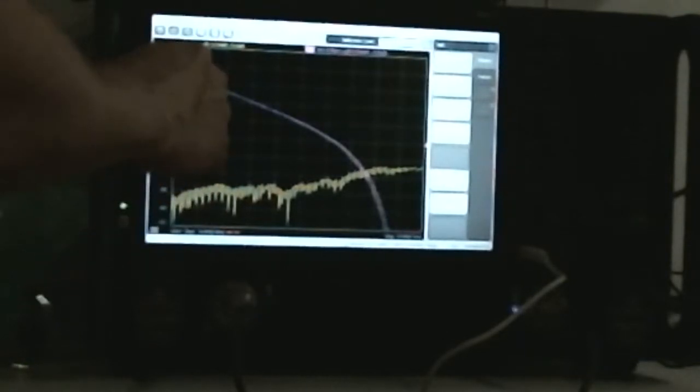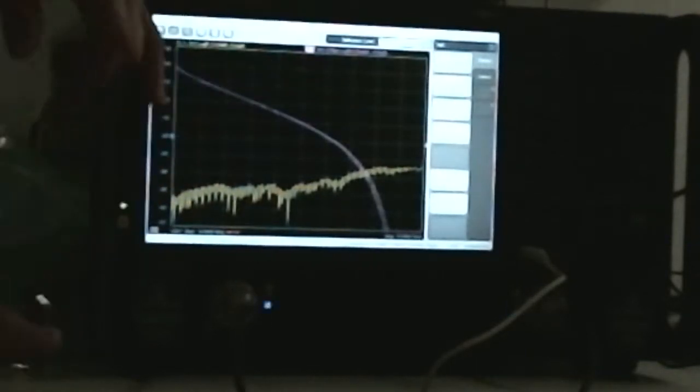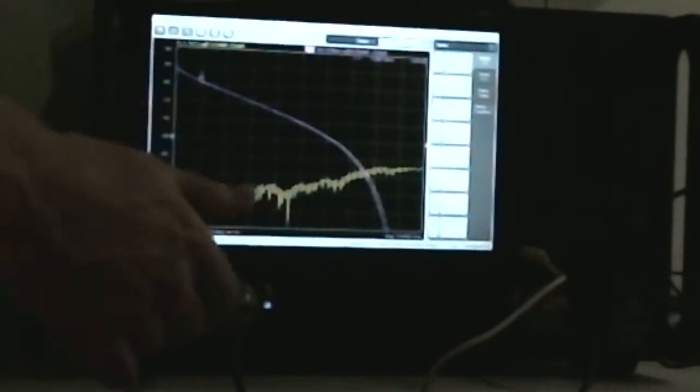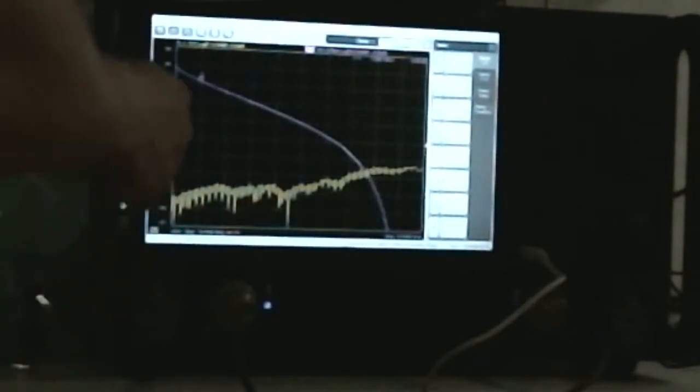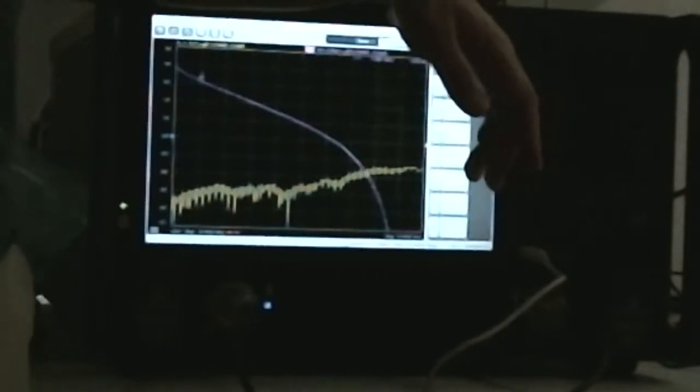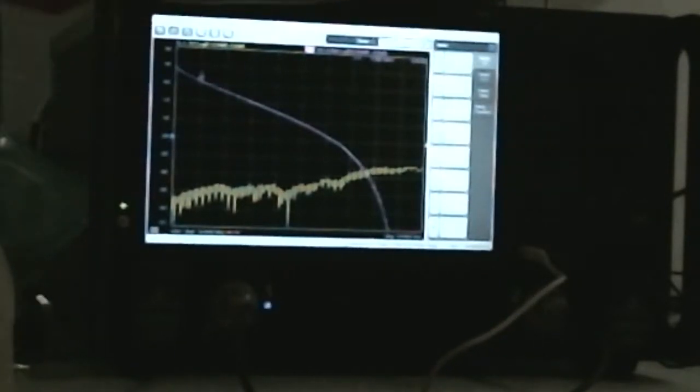So maybe if I look at the low frequency, it's not changing that much, right? If I put some markers on here, just to give you guys some rough ideas, anything below, I'd say like 1.4 gigahertz, is probably okay. But if I say, okay, I measured it here, and I come back, this is at that 8 to 10 gigahertz. I'm looking at sort of 2 or 3 divisions depending on where I position the cable. That's basically 1 to 1.5 dB difference, and that could be the difference between you having a really good project for your thesis and you having a completely unreliable design, right?